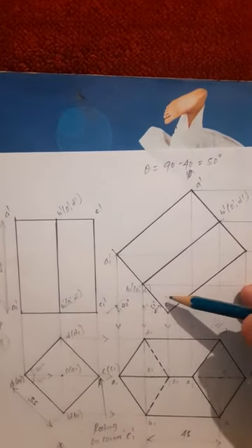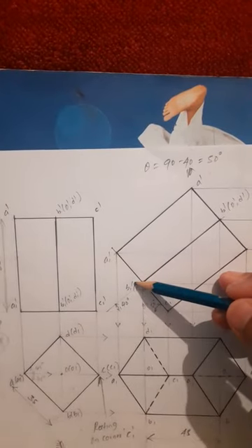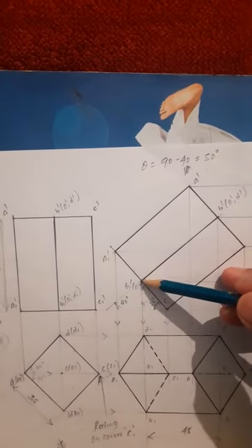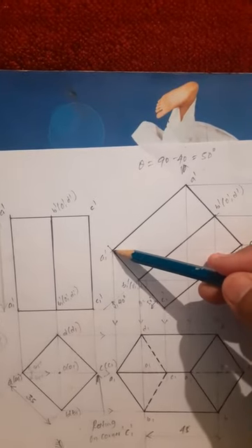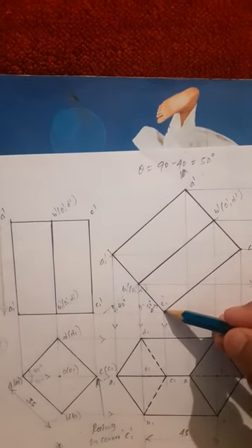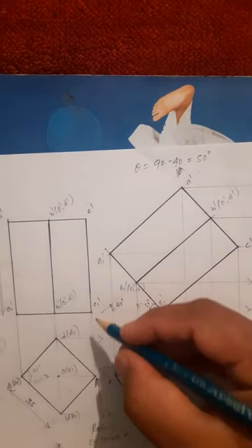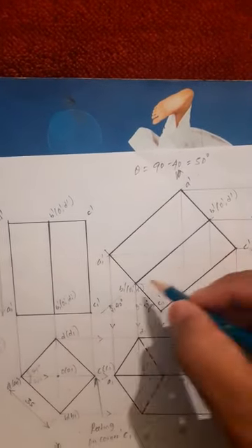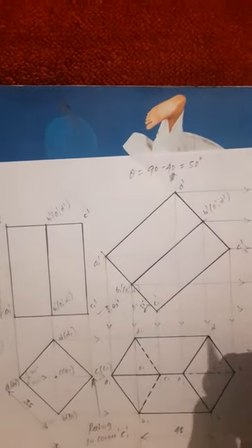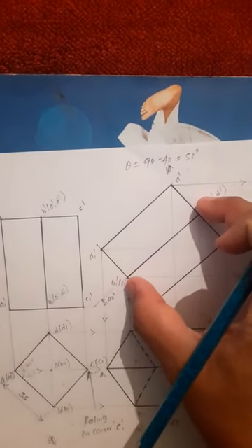Then already you know the C1 dash, B1 dash. Mark this on this point. B1 dash, O1 dash, D1 dash and A1 dash. From those corners, I draw, what is the angle here? It is a 90 degree, right? Draw all the 90 degree lines from those corners. Along the 90 degree, what is the axis length here?